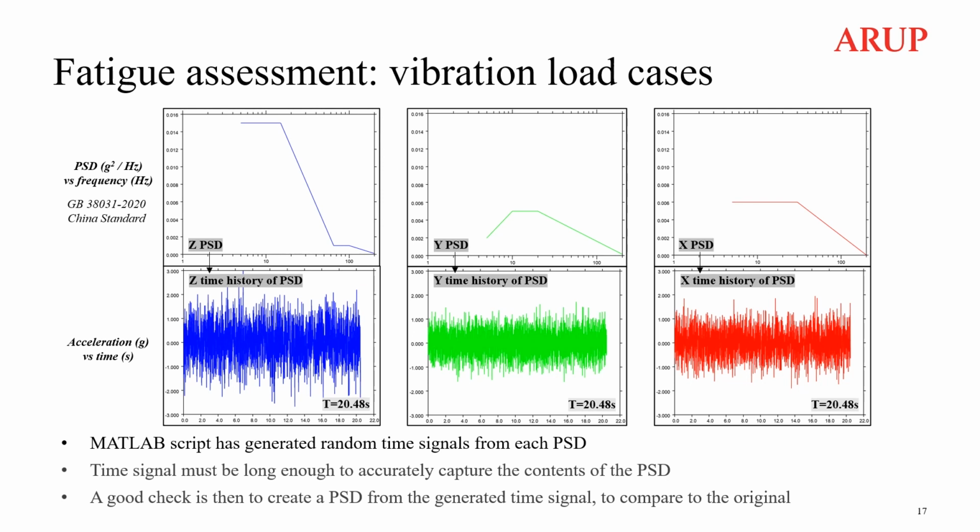It was necessary for the time signal to be long enough to accurately capture the contents of the PSD. A good check for this was to create a new PSD from the generated time signal and compare it to the original PSD. There should be negligible discrepancy.